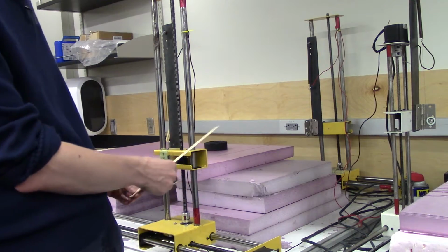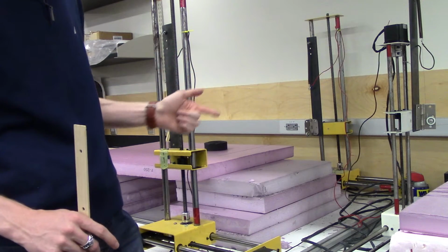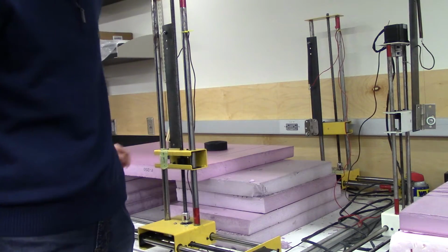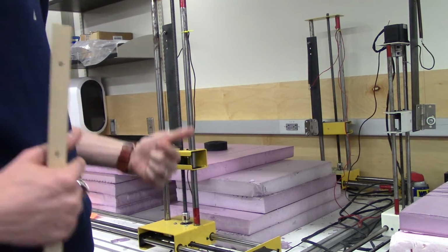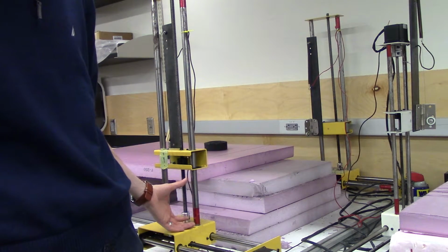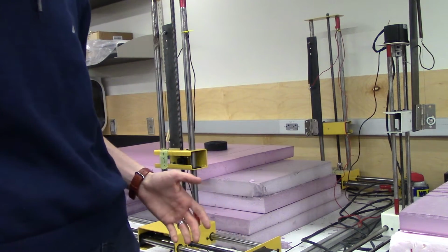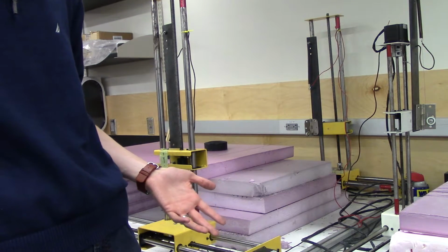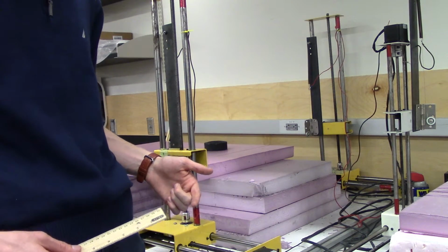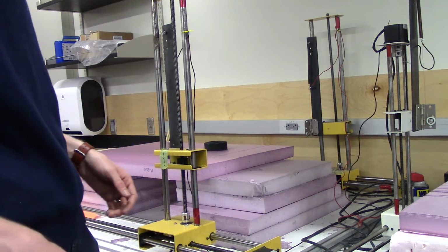Now I'm going to do the same thing for my y-axis, but for this one, not only do I want to make sure that the y is the same on both sides, but it is at the bottom of my sacrificial foam block. We've got this foam stacked up here so that if you do happen to cut down into it, it won't ruin the table, it's not going to ruin the foam cutters, and you're not going to run the carriages into each other. Again, you should never be coming close to the limits of these. If you are, then you need to really evaluate your design and look at how you can cut this better. Even for wings that have large amounts of sweep, there are ways to make that sweep a lot easier to deal with. If you have questions about that, feel free to ask.